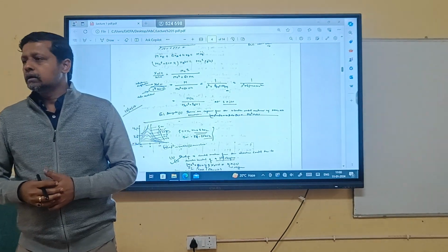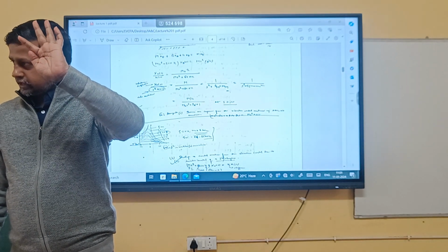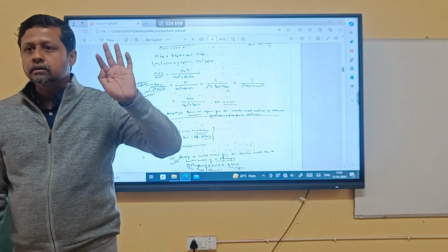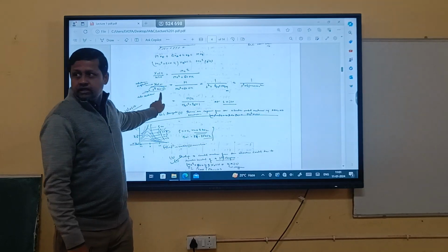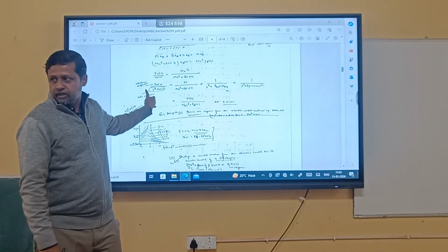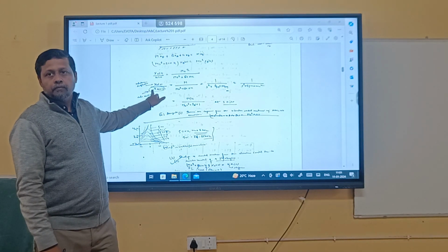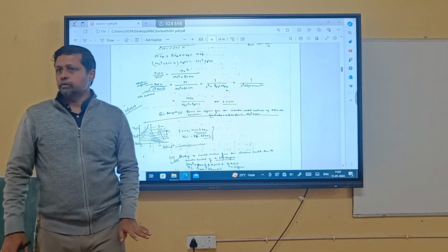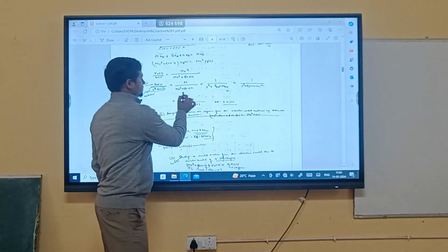Now where does s square come from? It is represented as two orders, right? So if x is the displacement, what is s of x? Velocity. What is s square x? Acceleration. Okay? So the input is acceleration. Now acceleration in the absolute form. ABS stands for absolute, right? Take it from my reference. So the absolute form of acceleration is the input. The relative form of displacement is the output. This is something I want. Now I can get it, but for that I need to modify this state.